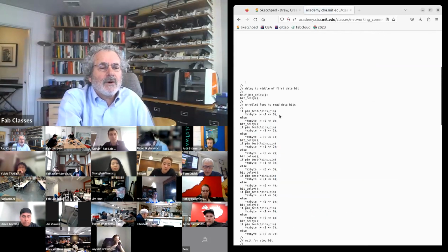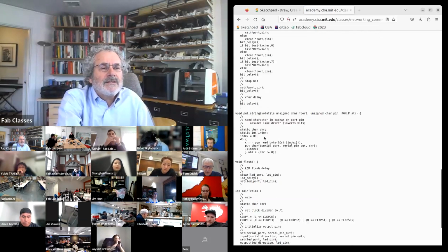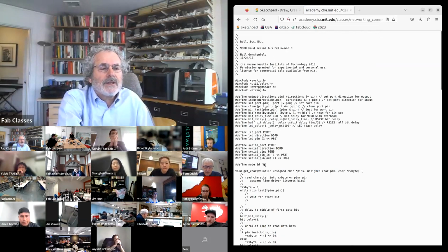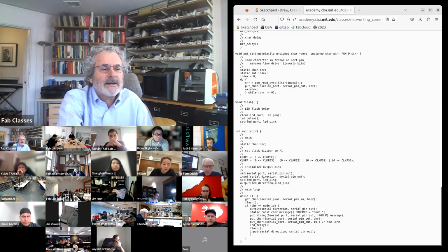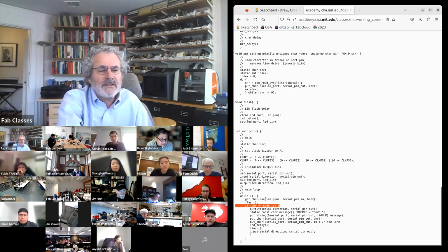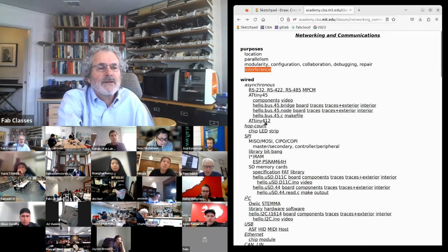And so in the code, each node has a hard-coded identity. Then in the software, it reads a character. That's the first flash. Then it asks, does it match my ID? And if it does, it sends out a message. That's with the Tiny 45.